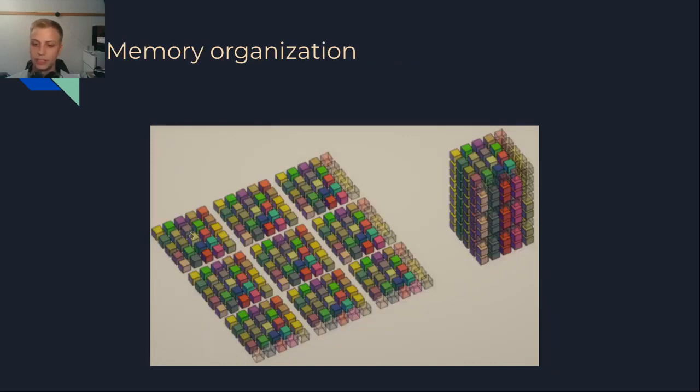Yeah, so the idea here is that in order to actually do a convolution, we need to extract all 25 neurons at the same time to do 25 simultaneous multiplications. So the first convolution will extract this one, and the next one will then go one to the right and extract that part and do the convolution again, and so on, and we'll store them.